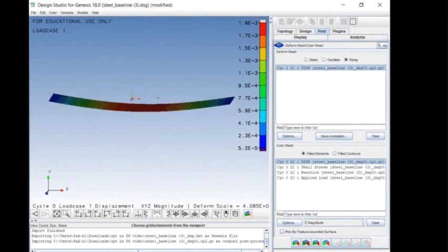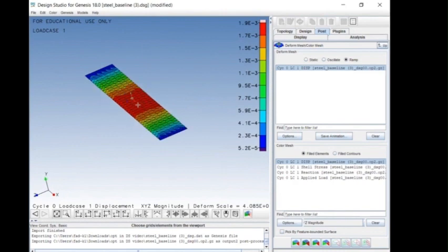So that's going to be our target stiffness. Okay, we've got this steel structure. Like I say, it's 3 mil thick. The loading on it gives us 1.9 millimeters of deflection in the center, so we can calculate the stiffness.